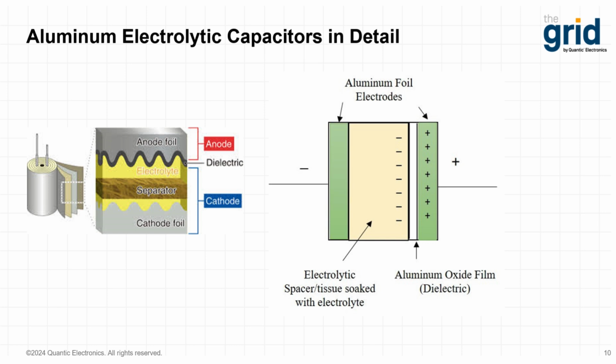Aluminum electrolytic capacitors that use a wet or liquid electrolyte are more common, but some use a solid electrolyte. The solid electrolytes are known for being more stable as they better maintain their electrical and thermal characteristics over time and are more vibration resistant. But solid aluminum electrolytics are not self-healing, which means they can prematurely short due to a fault or imperfection in the dielectric. In addition, solid aluminum electrolytics do not offer as high of capacitance values.